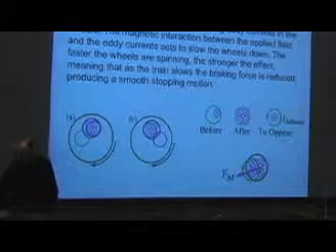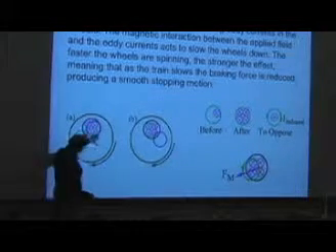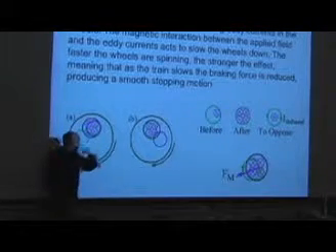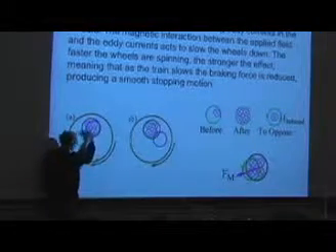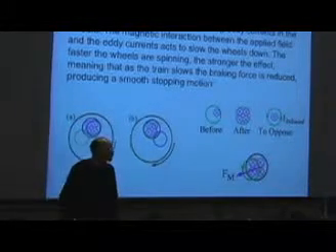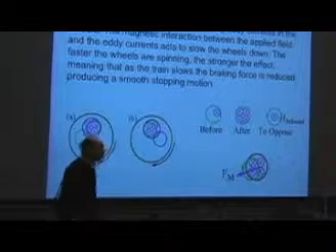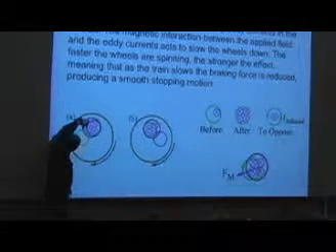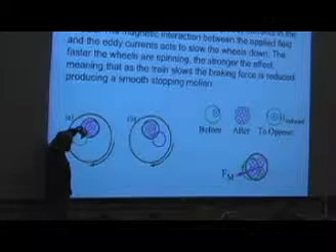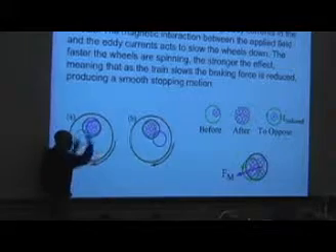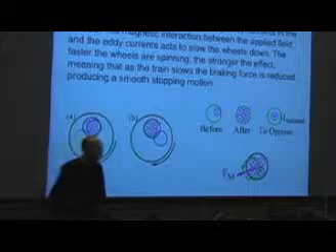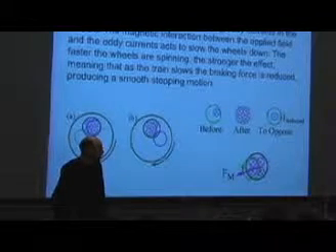Okay, and so focusing on this region of the wheel, we get a force in this area down and to the left. Well, the wheel is rotating this way. If we get a force here, we're going to get a torque on the wheel, which is in what direction? Clockwise or counterclockwise? If we apply force in this direction at this point here, are we going to speed the wheel up or slow the wheel down? It's rotating this way. We're actually slowing it down with a counterclockwise torque. Okay, so that's how it works.